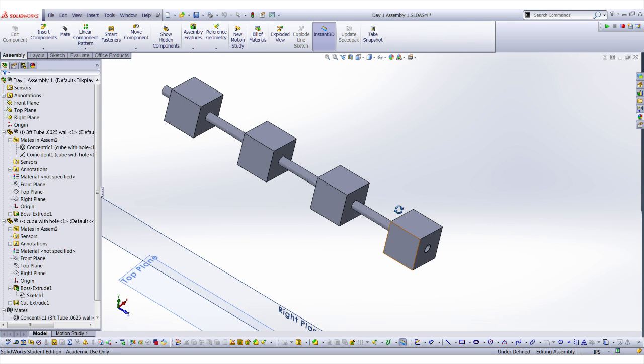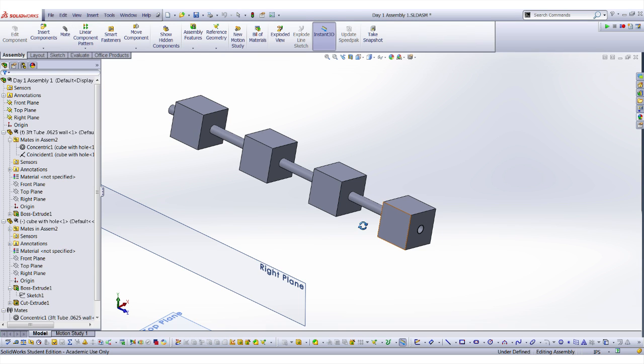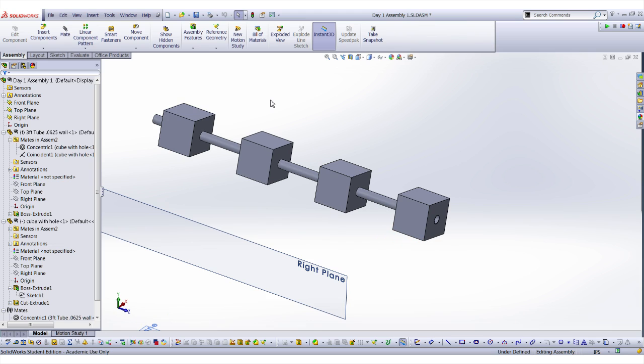So that quickly I was able to take a lot of volume off of those cubes, and it all updates and it all knows where everything is and it saves. When you save the assembly, every individual part in the assembly saves as well. So all the parts are updating all the time. So don't think you can put something in an assembly, modify it a bunch, save it, and then have the old version of the part. You won't. It's referencing those part files directly.